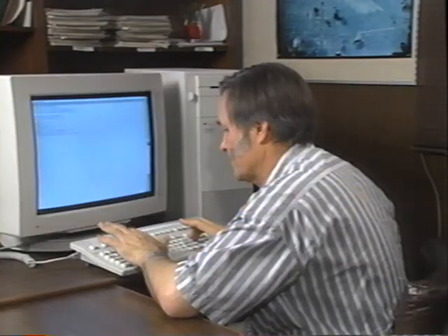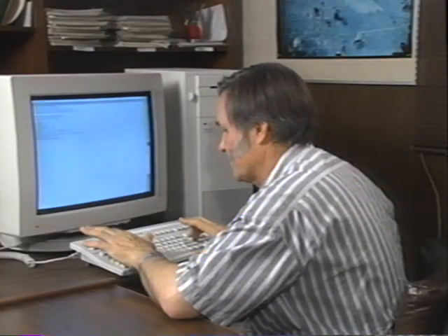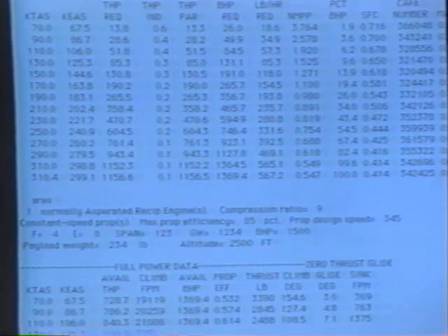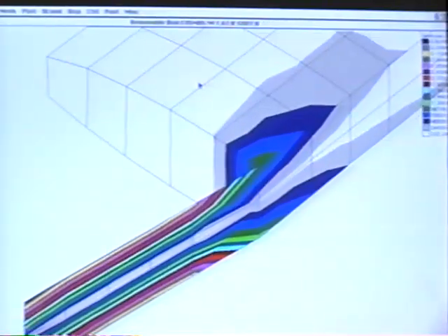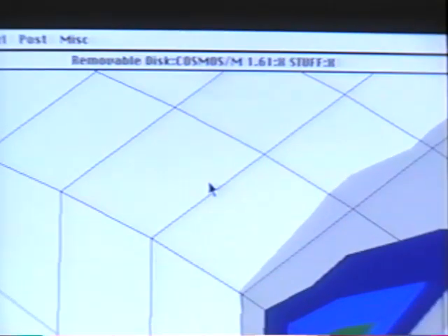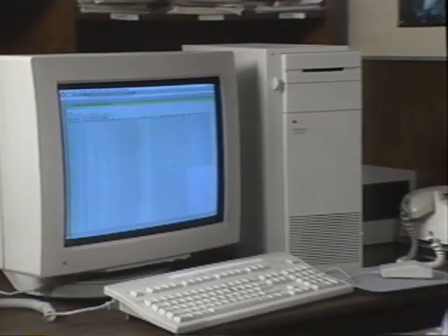Vellum is very intuitive, but there's no sacrifice in precision. Burt Rutan, for example, copies the Vellum data into other programs to run performance checks. He can do this because calculations Vellum generates use double precision floating point accuracy to 16 decimal places. And exporting these figures is seamless, quick and easy. Burt simply cuts and pastes the figures from Vellum into a performance analysis program. Further performance checks and finite element modeling programs such as Cosmos derive information from these original numbers. In the end, calculations appear on customized spreadsheets, such as Excel.